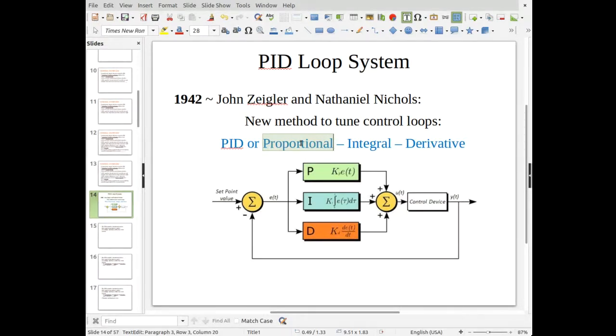The integrator and the derivative both have that dt there. You see the dt in the slide there for I and D. Those are delta t's, so that you've got that timer action. Those are only going to change every delta t, and we can set that just like we did in the previous integral lab.